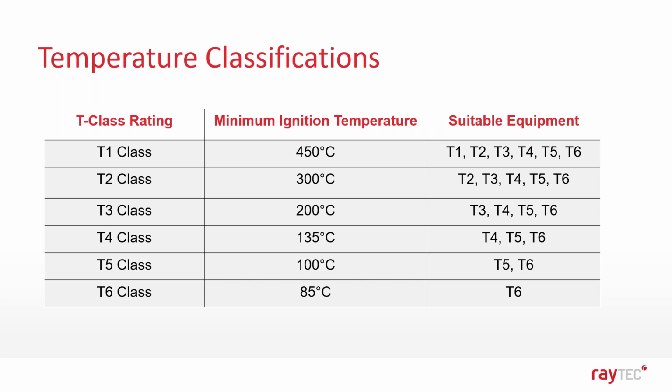As well as ignition energy, the other important consideration for explosive substances is ignition temperature. This is defined as the temperature at which a substance can ignite and sustain combustion without being initiated by a spark or a flame. It is sometimes incorrectly referred to as the auto ignition temperature.